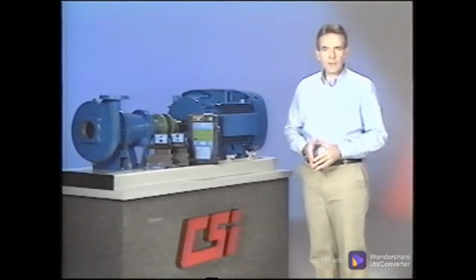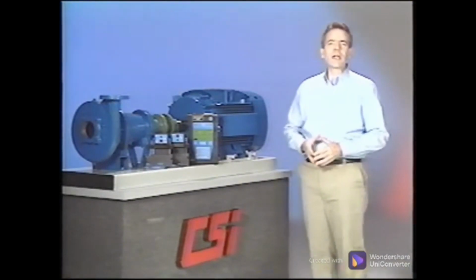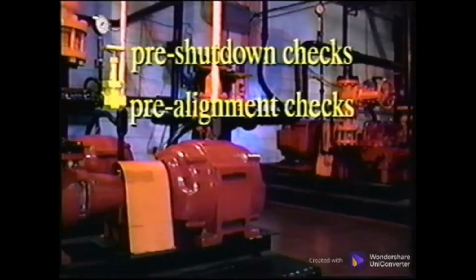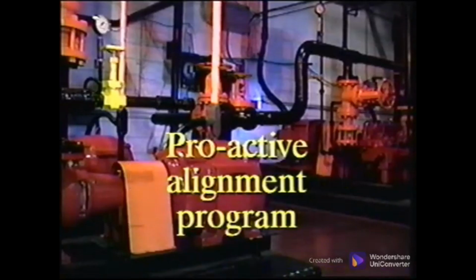Earlier, we posed a question about hiring a contractor and pointed out that tools don't align machines, people do. A good alignment job includes the pre-shutdown checks, including thermal growth, and the pre-alignment checks, including piping strain, soft foot, and bar sag if applicable. If these checks and corrections are made and properly documented, including the final machine positions, then you are beginning a proactive alignment program and not just performing alignments.